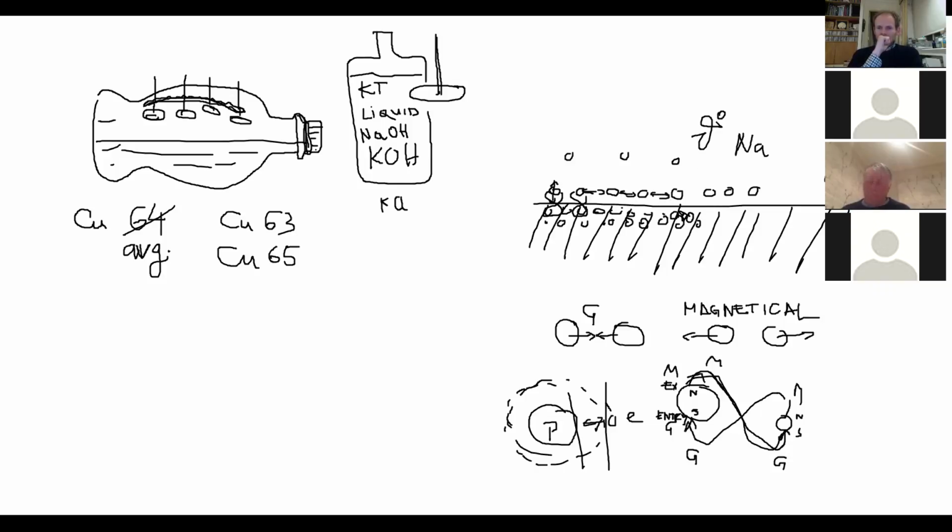It does not matter if we use a caustic method or a high temperature method. One of the ways to create these nanolayers is just to heat up the metal. You can use the flame of a torch at about 650 centigrade, or you can grow nanolayers by putting a clean copper plate in an oven, which you can heat up to 300 up to 700 centigrade somewhere.